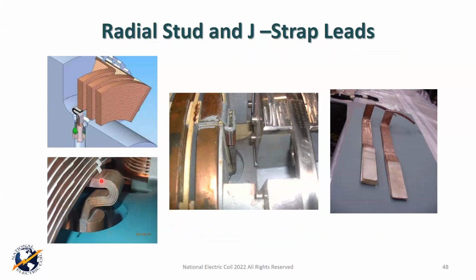Here's just a better up close picture of that. This is a beautiful joint. Got a nice gentle radius here. We don't have any of these conductors that are stressed tremendously. One of the problems on some of these designs, though, and some of the manufacture this braze to the stud of this shunt pack or this stack of laminations, they allow that braze to migrate through capillary action or whatever up into this area, takes away some of that flexibility. There have been a lot of failures because of that.